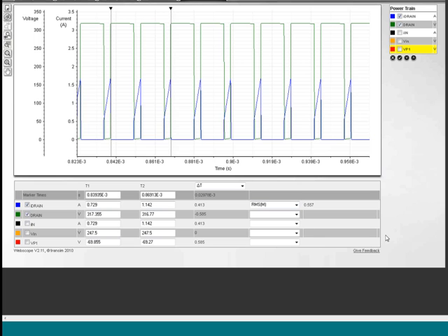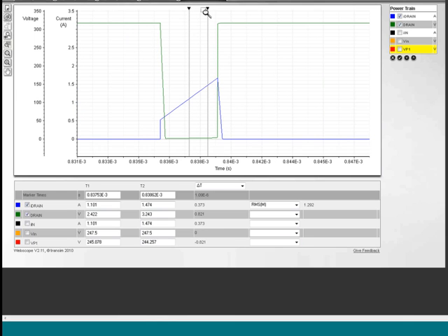But I can also look at the RMS value between the 2 cursors, and between these 2 cursors, the RMS value is now 557 milliamps. If I were to move these 2 cursors here, you can see that the drain current, which is the blue value, is now much, much smaller because I'm centering around 0. If I were to focus on the areas between here and here, since I'm really struggling to get to that, I'm going to zoom in on that area. So here I can look at the drain current, and you can see by changing between these 2 values, I can easily pick that one.